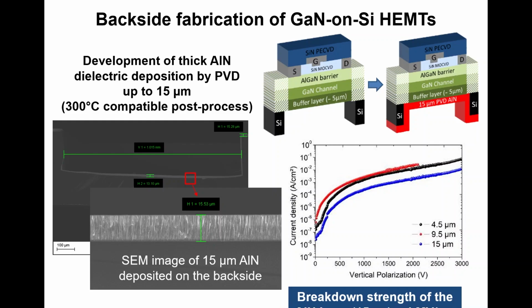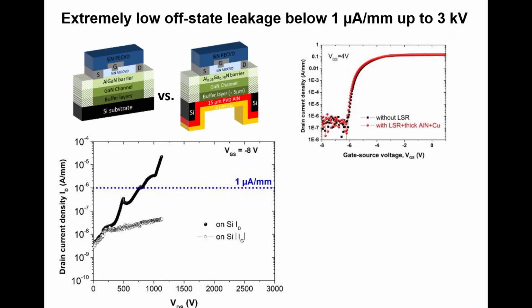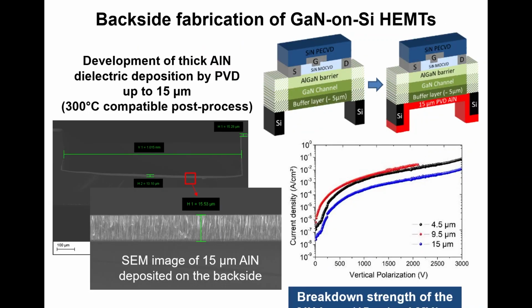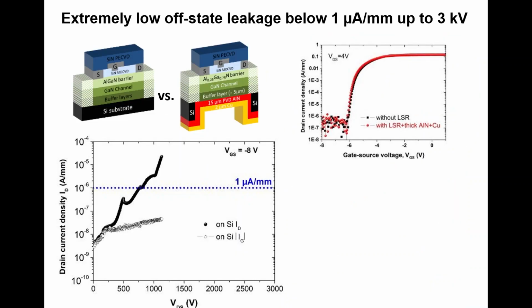You could imagine that this aluminum nitride, looking at how it looks like here, is pretty poor. But aluminum nitride is amazing. Even a poor one provides you 4 megavolt per centimeter. If it's a good one, it goes to 10, 12. But the poor, low temperature one is still way above gallium nitride and silicon carbide. That's really an amazing material. And of course, thermal conductivity is not good, so I'm not talking about that here. These are columns, but that was just to focus on the breakdown.